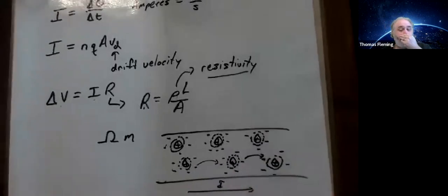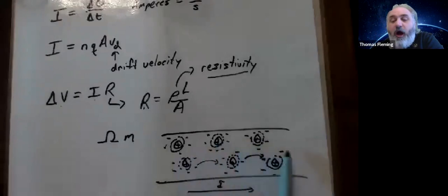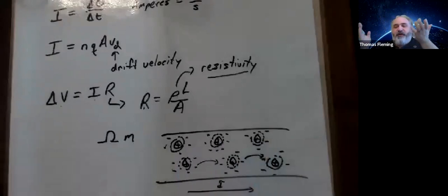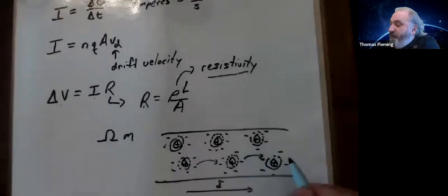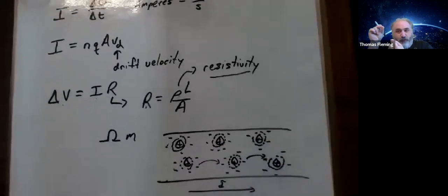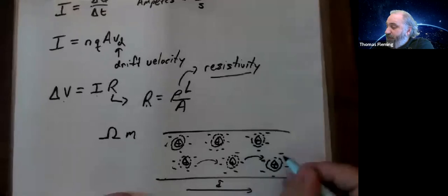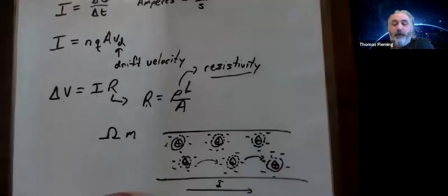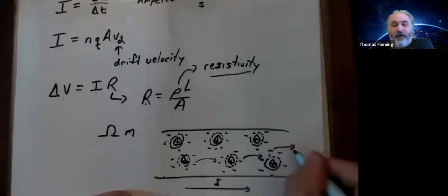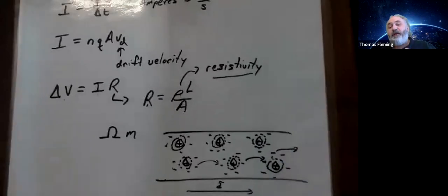in my wire. And what's going to happen is the higher the temperature of your wire, the more you're changing which states are occupied by your electrons. So maybe if I get this particular wire hotter, some of these electrons that are down in the low energy states and can't move from atom to atom will get enough energy to move to a higher orbit. And when they do, they'll hop up to those higher orbits, and now they can hop around themselves. So the charge carrier density N might get larger when you heat your wire up.